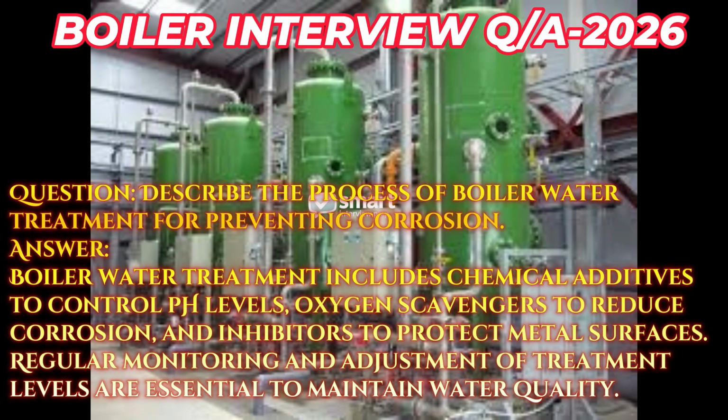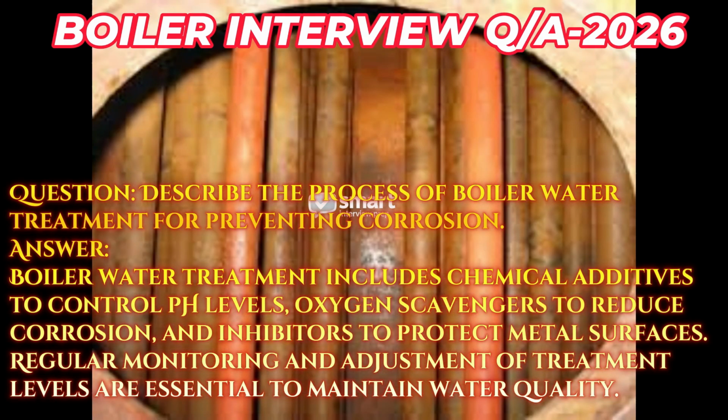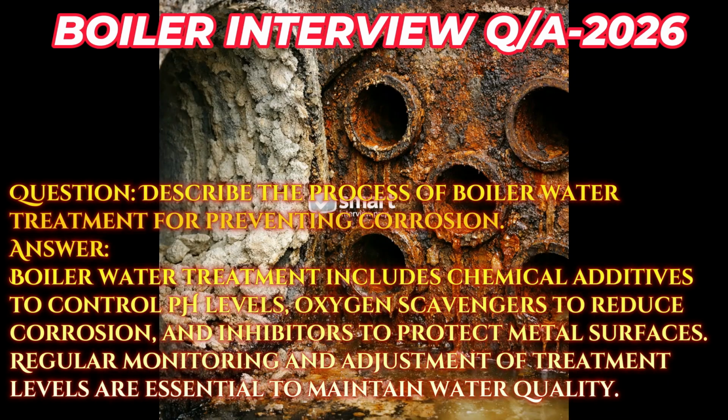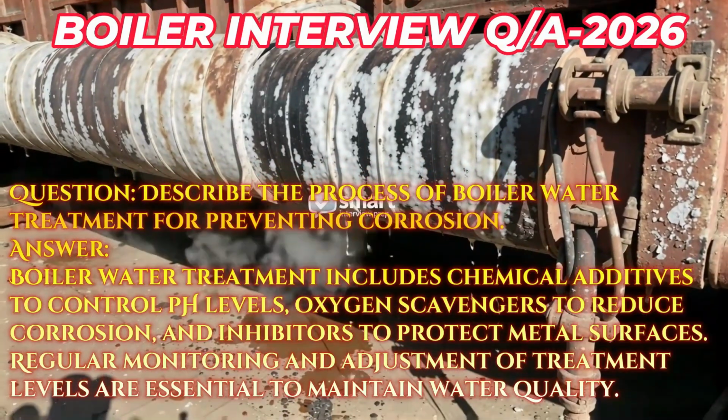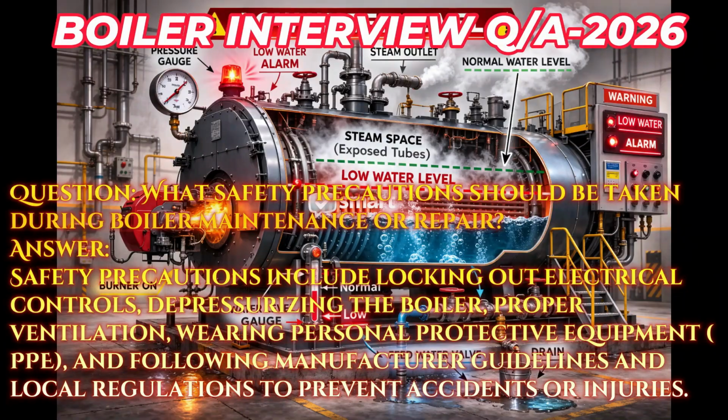Question. Describe the process of boiler water treatment for preventing corrosion. Answer. Boiler water treatment includes chemical additives to control pH levels, oxygen scavengers to reduce corrosion, and inhibitors to protect metal surfaces. Regular monitoring and adjustment of treatment levels are essential to maintain water quality.